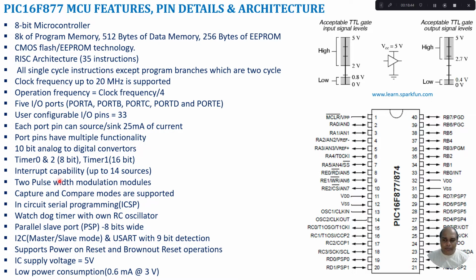So in order to put the data from your computer into the program memory of your microcontroller, we need to do the programming part. Here I can do the programming in circuit. When the IC is in the circuit itself, we can directly dump the opcode file into the program memory of your microcontroller through pins.